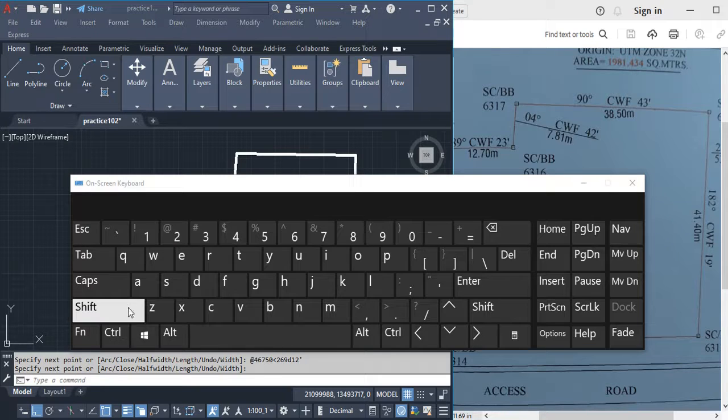This is your at, and then your degrees, how to get it, this particular one here, say 90 degrees. You hold down this shift and press this less than button, and then this sign here will appear on your status bar here, just like we have it here, and then you type in your 90D, being the 90 degrees, 43 minutes.